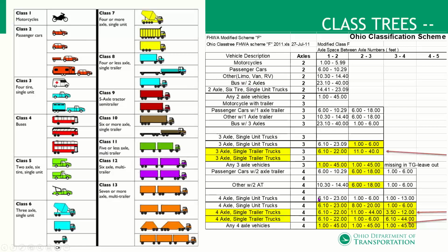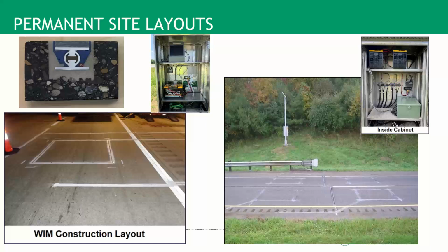This is just showing you this distance, so it must be a motorcycle. Or there were 4 axles, and the axles were spaced this far apart, so that's probably a passenger car with a 2-axle trailer. So this is how those things are broken down in order to get good data out of a tube count. And this is where, if those tube counts are not installed correctly, or the software being used doesn't know how to break this down well, or it gets extra bounces in the air hoses, you get bad data. But if it's done correctly, you can get great data every day of the week.